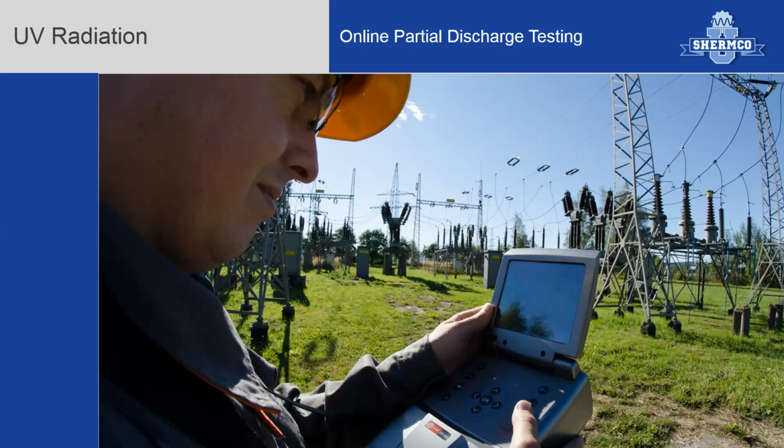Now, if he's pointing it toward, let's say, a bushing, and at the tip of the bushing, he's finding very repetitive, continuous little bursts of white light, what he's probably witnessing is the ultraviolet radiation occurring from the corona discharges into the atmosphere. Now, let's say he's also viewing that same bushing and he sees a stream of flashing light, little bursts of white light, repetitive, and following the same path. What he is probably visualizing is surface tracking going down the bushing. So the camera is very useful and allows us to visually see exactly where the surface tracking or the corona discharges are taking place.